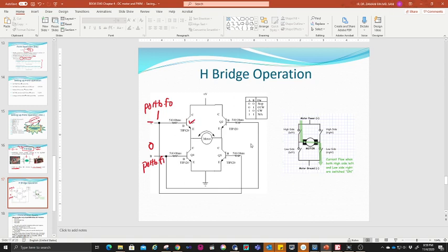And then this one is going to be turned on. So this one is turned on, so the current will go through this one. This is 0, there will be nothing here. This is also 0, there will be nothing here. Then the current will flow to this one, and your motor will move in one direction. So this is why you need to put 1 and 0 here.